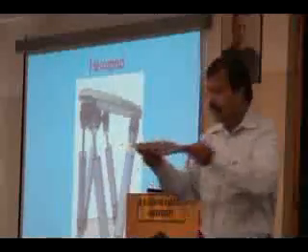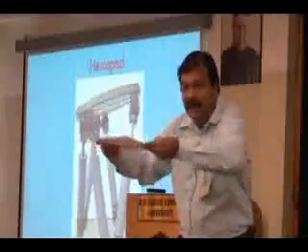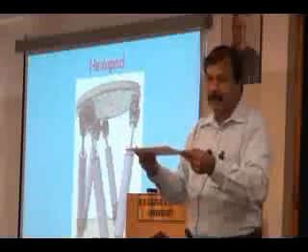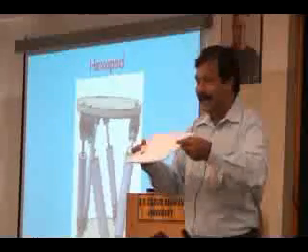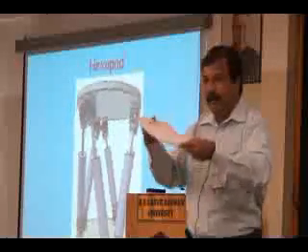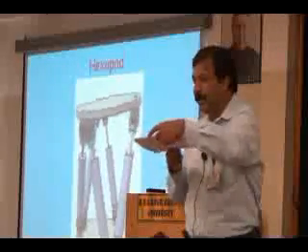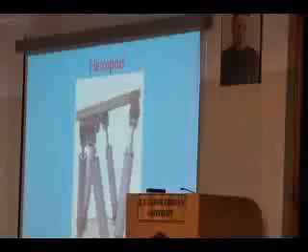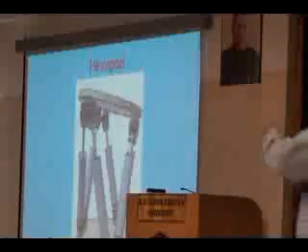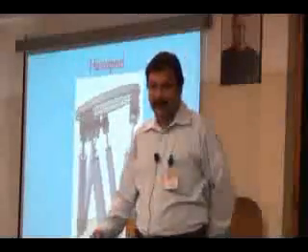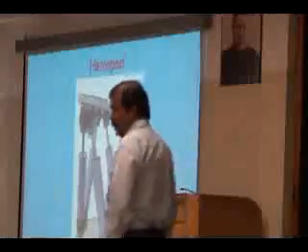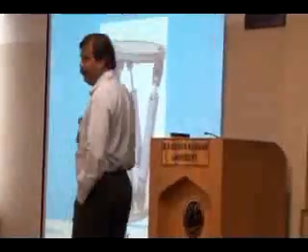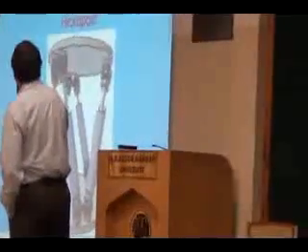It can move along the x-axis, move along the y-axis, move along the z-axis. Now, it can rotate about the x-axis, it can rotate about the y-axis, it can rotate about the z-axis. It can achieve all 6. That is why I need the 6 cylinders. For achieving 6 degrees of freedom, I need 6 actuators. So this particular arrangement is called... I'll come to the name later because that will betray something else. Let us go to the next slide and then see.